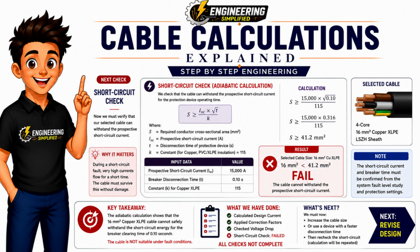Using our fault current of 15,000 amps, a breaker operating time of 0.1 seconds, and the copper XLPE constant of 115, we calculate that the minimum conductor size required is 41.2 square millimeters. Our selected cable is only 16 square millimeters. That means the cable cannot safely withstand the fault energy. So although it passed the earlier checks, it fails the short-circuit calculation. This means we must revise the design.